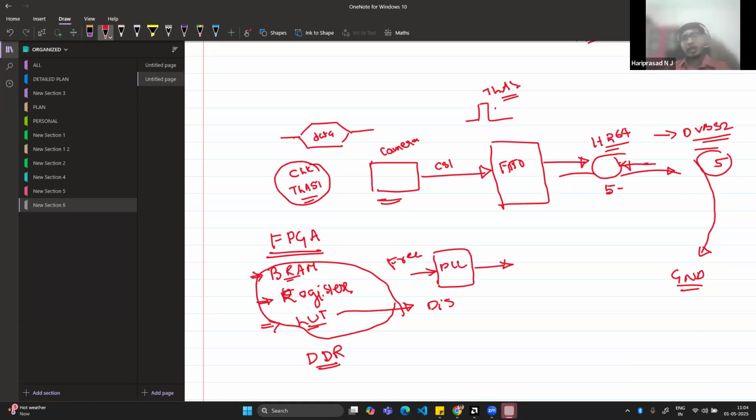But let's say I have a drone application that keeps monitoring real-time data and has to store it. FPGA and DDR are all volatile, right? As soon as it reboots, all the data is erased. So in that scenario I will go for flash memory.